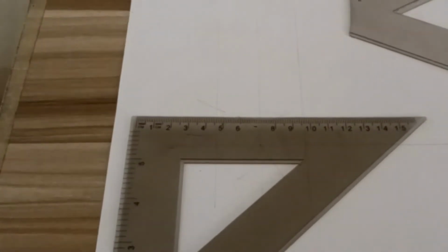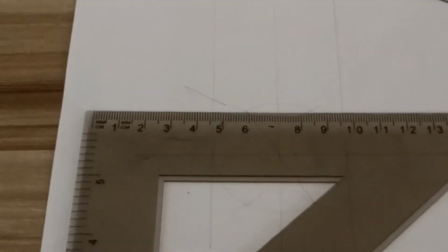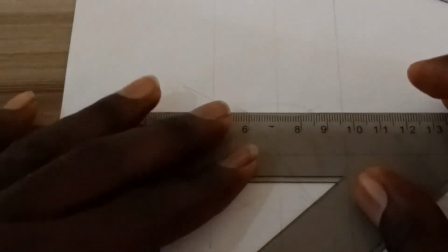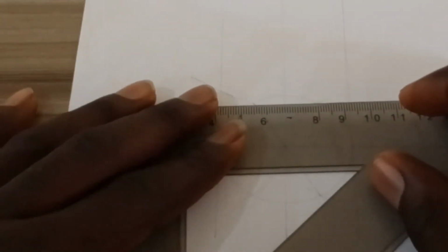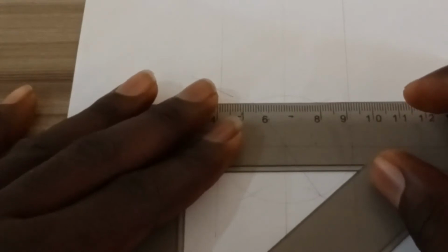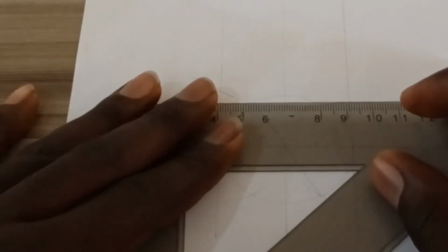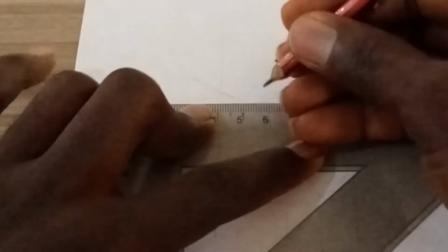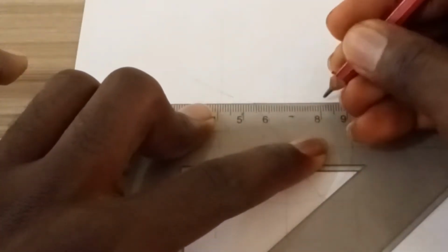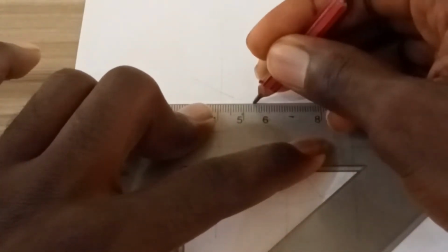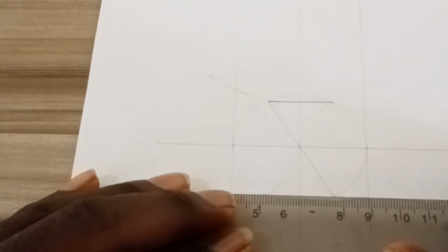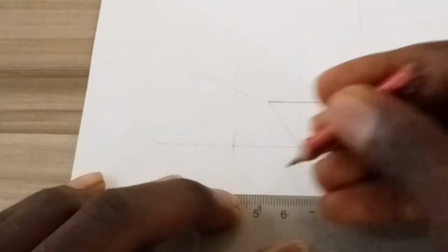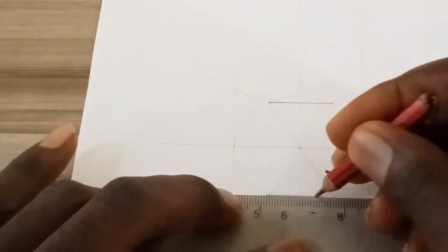You don't have to measure. All you have to do is put the pin at one end and just extend the radius. Cut. Remember, a hexagon has 6 sides. So we're going to draw the first side. Place your ruler and draw the first side, and please remember, the circle is to be drawn with a thin line, because the circle is only a construction line. The main thing we need is a hexagon.